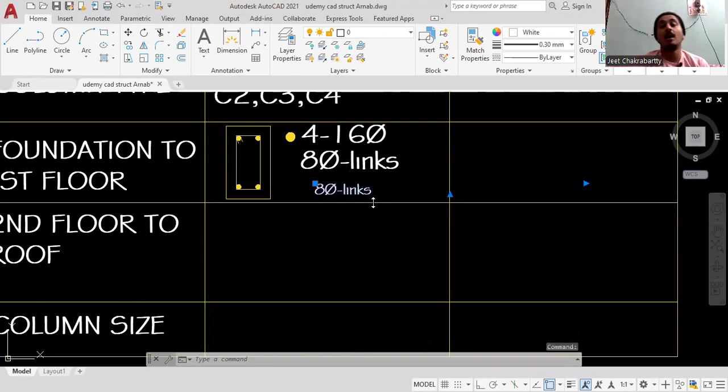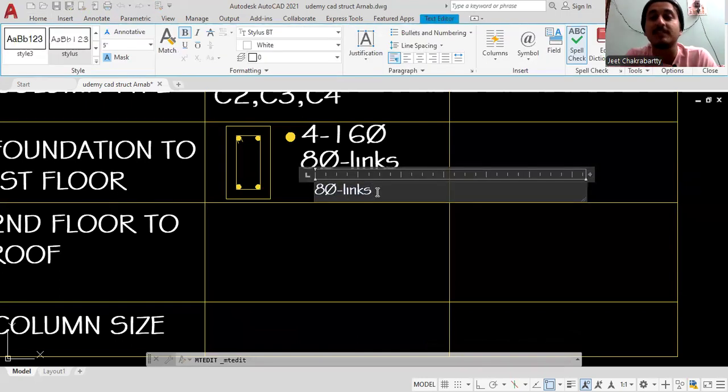Now we will check which type of spacing we will give. First, in my lecture you will see in the beam section there is a stirrup concept lecture, so you will follow that. I have described it there. Near the support, for a column the support is the plinth beam or the beam, the shear force is maximum and in the mid portion the shear force is very less.